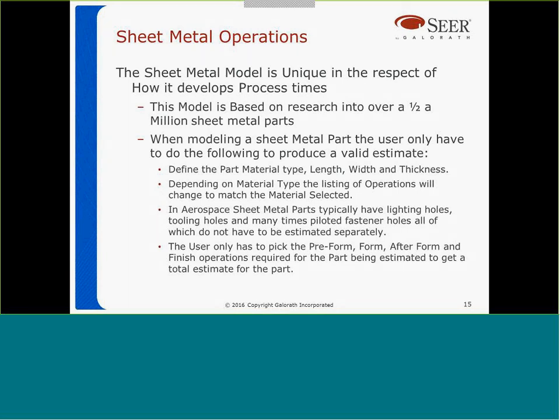So what we do is select the forming process, or in the case of CATIA, the type of part. You can make up templates for types of parts that take certain forming and after forming operations and get valid estimates by reading data from CATIA: the material type, thickness, and the area, the length and width. It will automatically produce an estimate based on the quantity presented by the user.